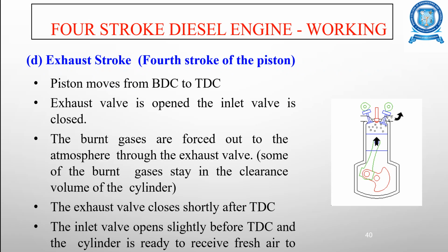And the final stroke, that is the fourth stroke, is called the exhaust stroke. Here the piston moves from the bottom dead center to the top dead center. You can see the exhaust valve is open and the inlet valve is closed. The burned gases are forced out to the atmosphere through this exhaust valve.